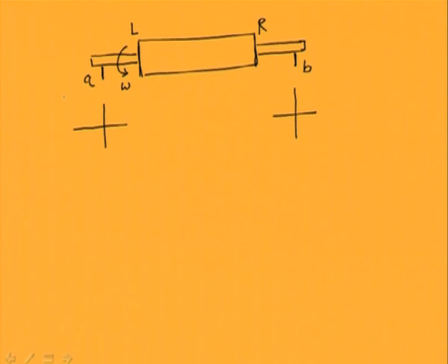Let us say we got L1 as the vibration response at the left bearing, and its phase is gamma 1. Displacement, velocity and acceleration are vector quantities, having magnitude and phase, so I have represented the vibration measurement as a vector. In the right plane we have this measurement, and the angle is, let us say, delta 1.